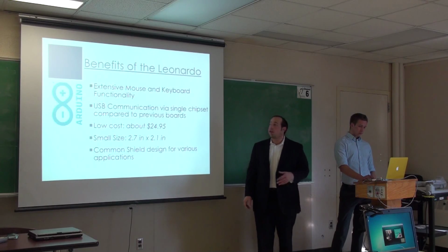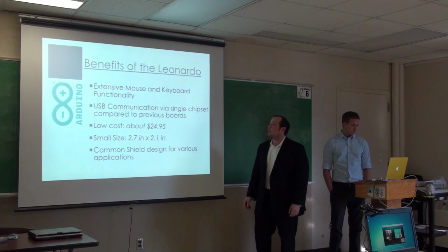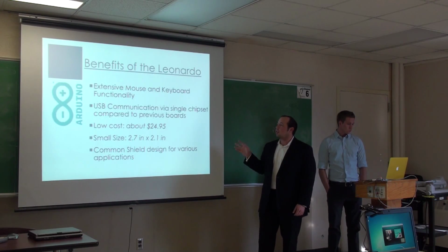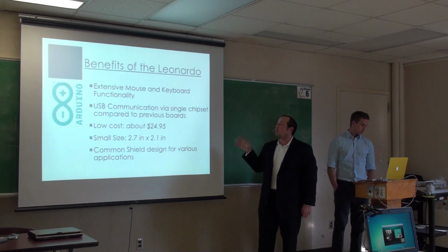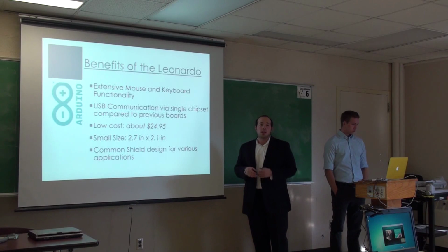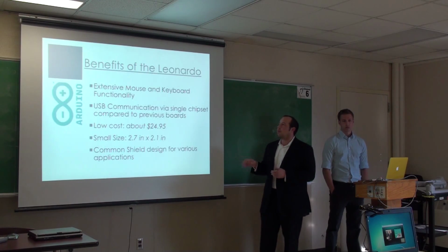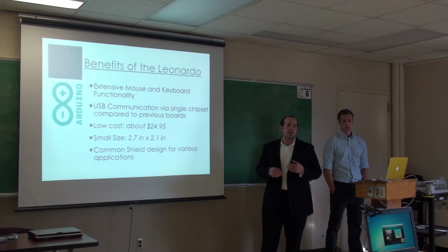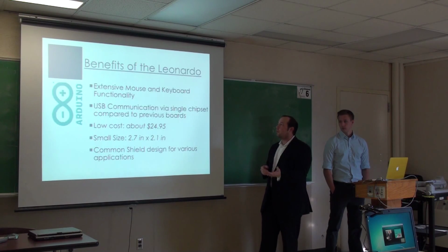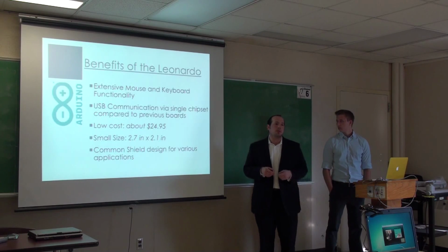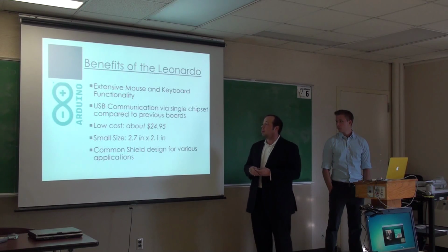So some of the other benefits of the Leonardo that we can talk about is because of that USB communication and processing is on a single chip, you have extensive mouse and keyboard functionality, where a lot of the libraries that you'll see for this Arduino platform is that it'll behave kind of like a USB mouse or a USB keyboard when you actually put it into the computer.